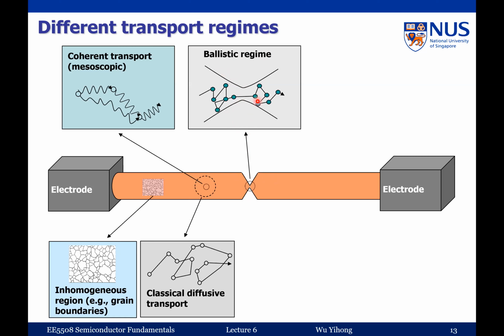In an actual measurement, you have to put one electrode here and another electrode here, right? So in this case, you basically measure the contact resistance between your electrode and this small opening. That's because your electrode is large enough, and this electron has to establish equilibrium with the electrons inside this electrode, right? But when this electron tries to jump from here to here, it will feel the resistance here because there's some sort of constraint here, right?